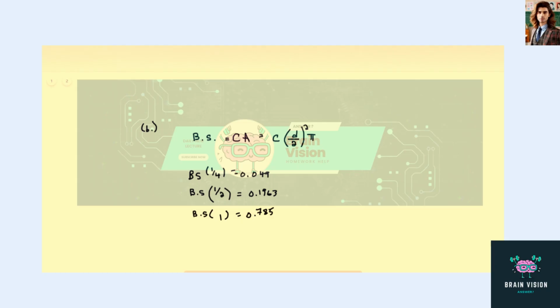Now, it also asks us for a good value for 9/16 inch, which is not logged in the table. And so the way I did this is I took the safe load value for 5/8, which is just above 9/16. And then I add it to the safe load value just below, which is 1/2. And then I'm going to divide by 2. So essentially, I'm just taking the average of the values above and below 9/16. And when I do that, I get a value of 240.35 kilonewtons, which is what I would use for the safe load value of 9/16.